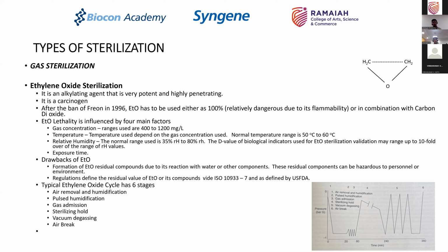Why is it not a constant value? Because for the presence of humidity, what do you need? You need air. But now you remove the air partially, and there is some amount of air and moisture present inside the chamber. There are situations where that humidity will fall and will not be constant. So what you will do is humidify it by sending in sprays of moisture. You will probably bring the humidity to say 54% or 55%, which is the target humidity in this case.